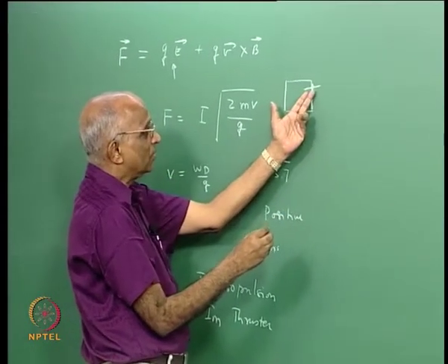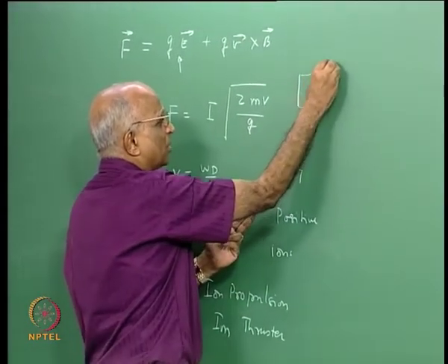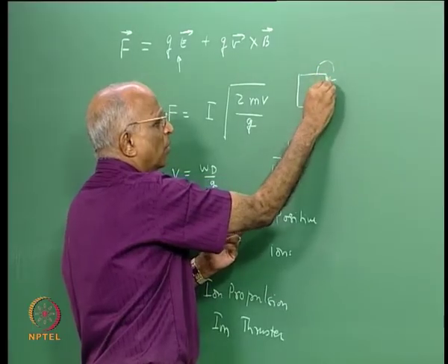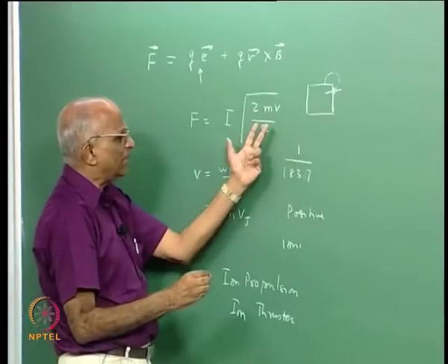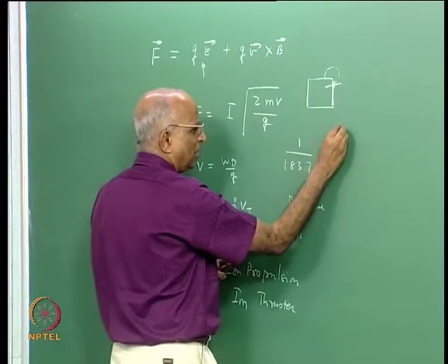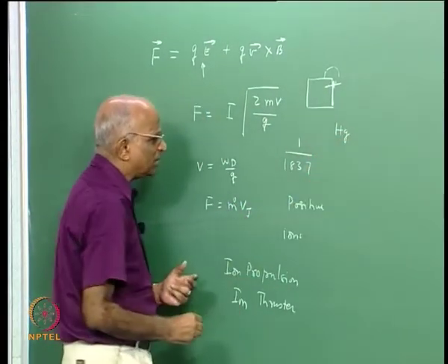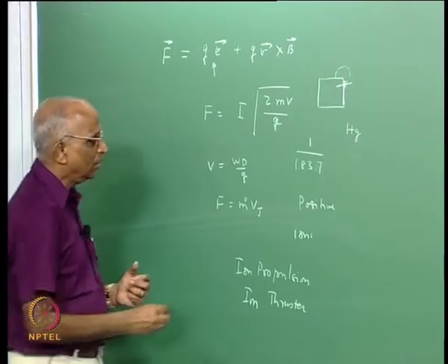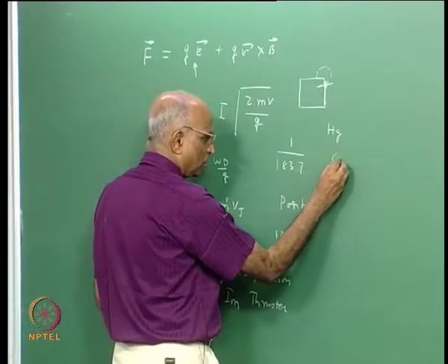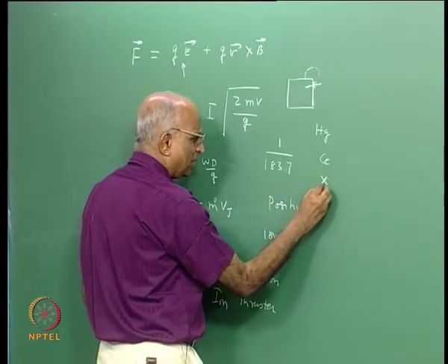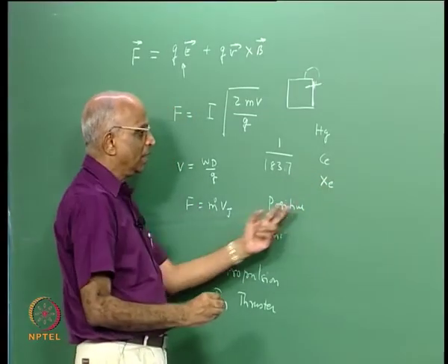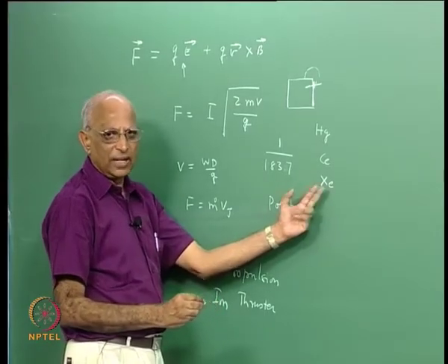If mercury is let off from the spacecraft it will form a monolayer on it and make it opaque, so mercury contaminates, and therefore mercury is generally not used. It was used in the earlier spacecraft and is no longer used. Cesium was also used but no longer, because it is a reactive metal, and what is universally used today is xenon, which is a noble gas.